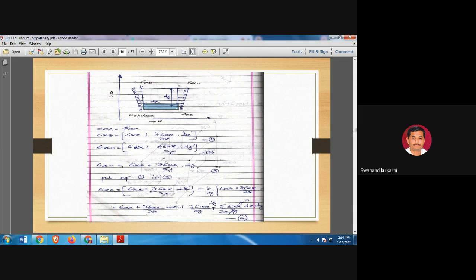Is it okay? So over this distance dx, you can understand here that at point A and at point B, how it is different. At point B, it is sigma xb, and sigma xb is the stress at point B, which is influenced by the position which is at a distance of dx from A. That's why we are taking the differential equation, because point B is exactly in the direction of x from A. So that's why we are considering the partial differential equation.